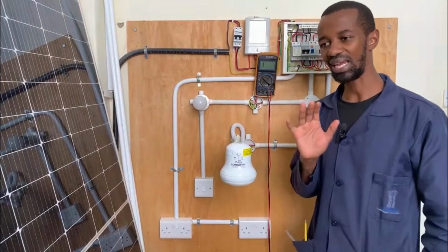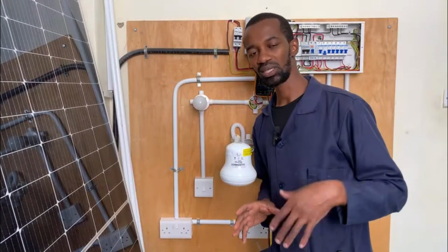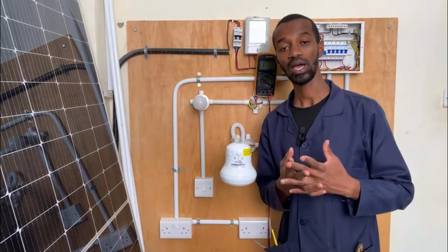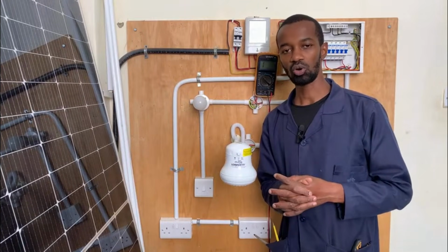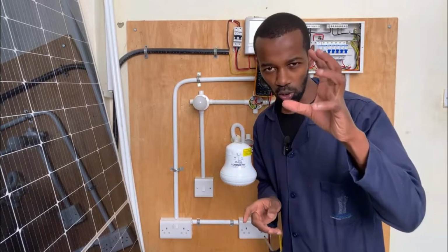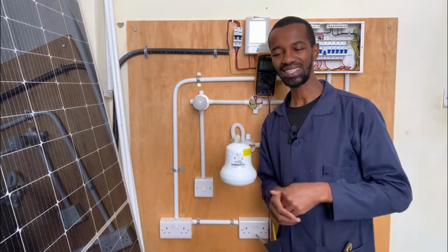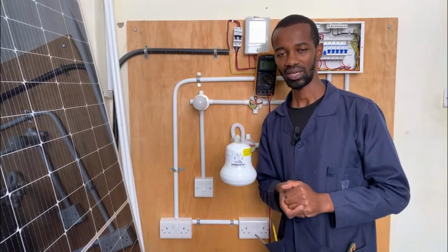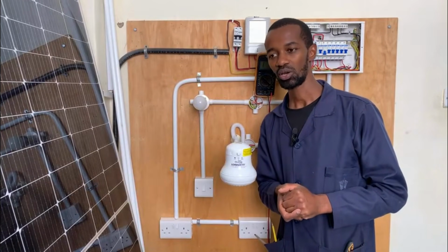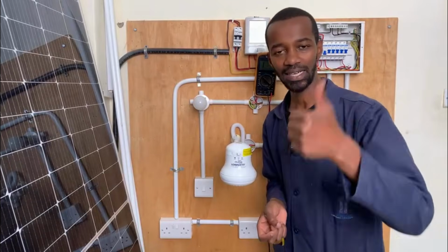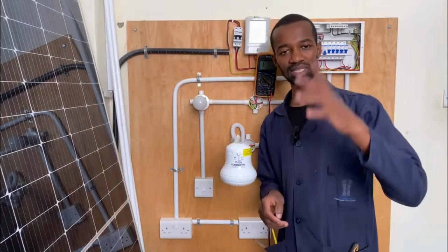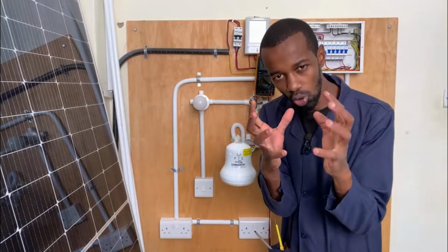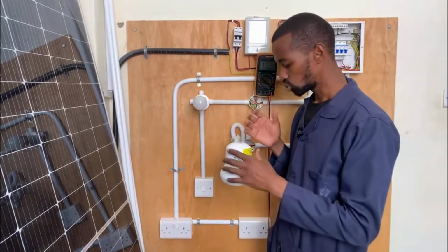For instance, say the lighting in the sitting room, or probably the security lights, were not powering on. These security lights probably have 4 switches, I'm just assuming, or they are served from a photo cell. So all of them are not powering on. You narrow down to the photo cell, or you can take individual lights and start powering them on, but that will be tedious. Simply isolate the whole circuit from where the MCB has tripped. Get the continuity readings. Do the same for sockets. Do the same for heaters in that home. Normalize narrowing down to the culprit.